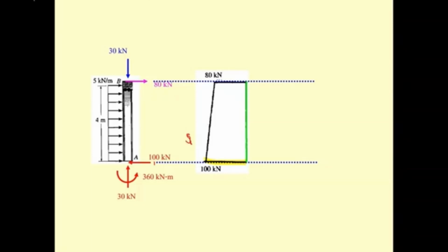It's going to be the negative of minus, this is -5. Okay, and you have the 80 here, so this is going to move this. That means the value of the shear here is supposed to be 80. And if you don't believe that this one is going to be 80, you can compute to check it easily.